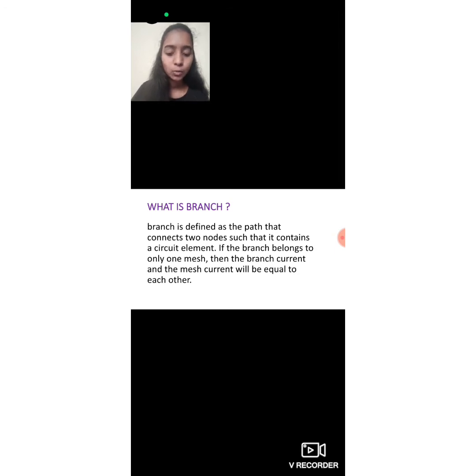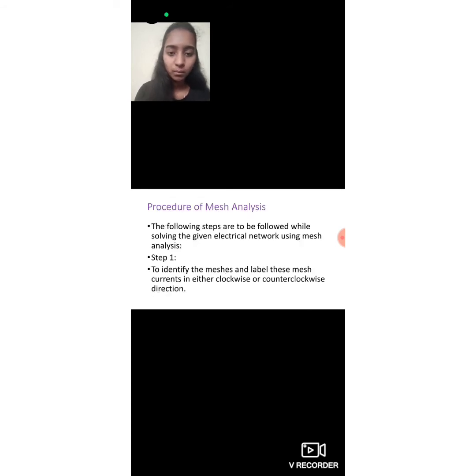So the node voltage method provides an algorithm for calculating the voltage at the nodes of a circuit, provided one can specify the connectivity of elements between two nodes. Then one can write down a set of simultaneous equations for the voltages at the nodes. Once these voltages have been solved for, the currents in the circuit are calculated via Ohm's law.